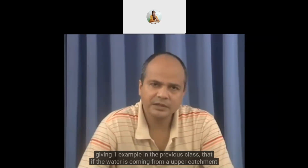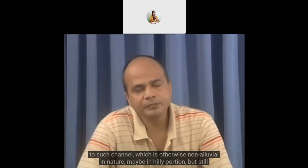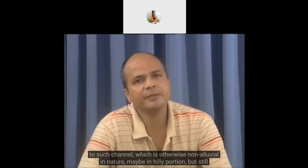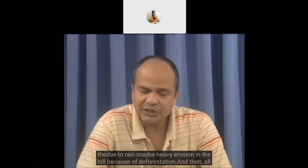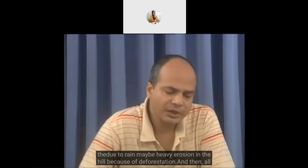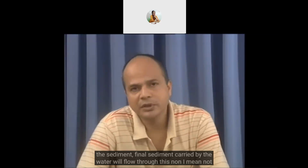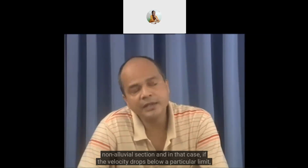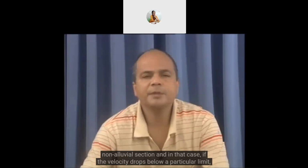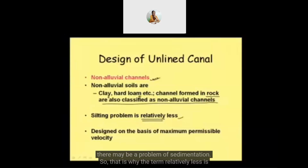But as I was giving one example in the previous class, if the water is coming from an upper catchment to such a channel, which is otherwise non-alluvial in nature, maybe in a hilly portion, still due to rain there may be heavy erosion in the hill because of deforestation, and then all the finer sediment carried by the water will flow through this non-alluvial section. And in that case, if the velocity drops below a particular limit, there may be a problem of sedimentation. So that's why the term "relatively less" is coming. It can be there, but generally it is less.